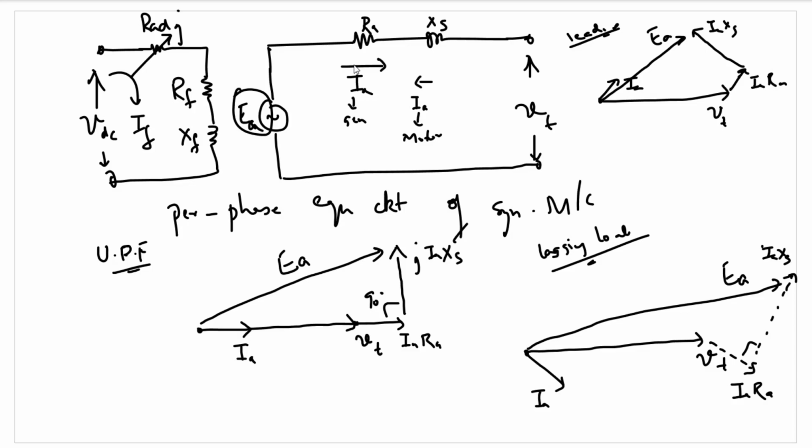Now we can combine the reactance due to the self-inductance of the armature winding and the reactance due to the armature reaction of this synchronous machine into one single term, XS. The synchronous reactance is an important term in the case of synchronous generators, based upon which we understand the stability and the power equations of the synchronous generator.